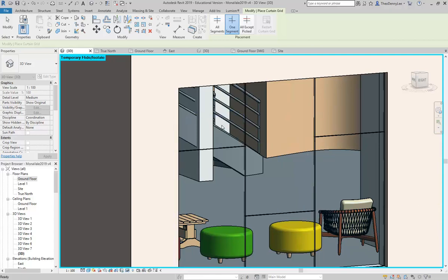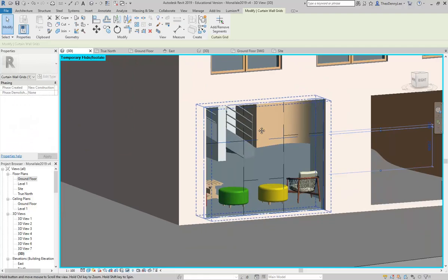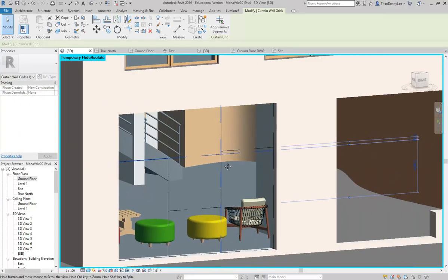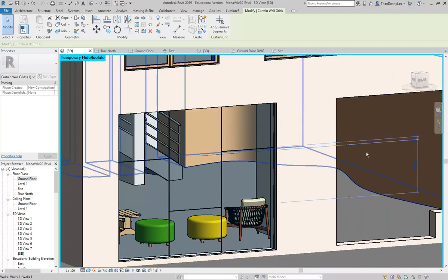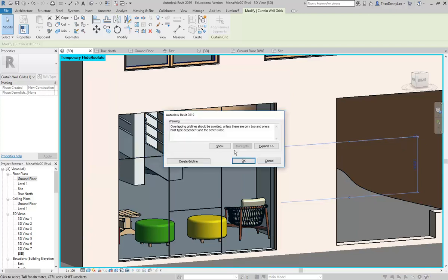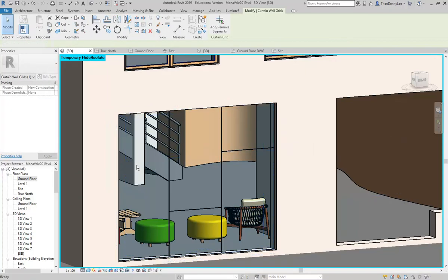There we go. Now it didn't go in at the right height. This one's 900 from the top, so I can always select that now, and you can see it's not giving me the dimension from the top, but this dimension over here is measuring to that other grid line, so I can make that 0. And oh yeah, now here, sorry, this is where you get an issue because it doesn't like overlapping the grid lines, so I'll show you a better way.